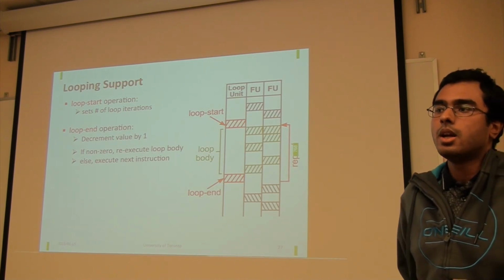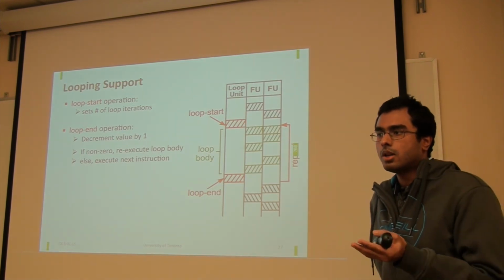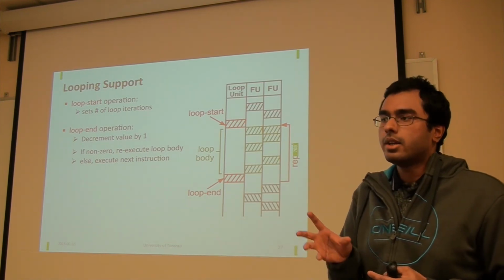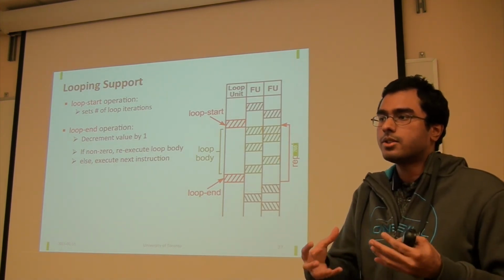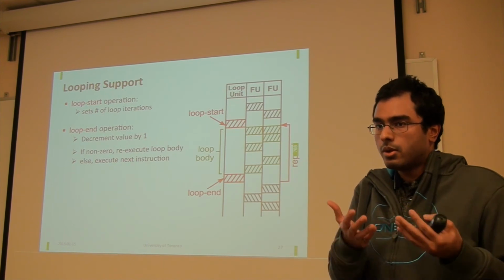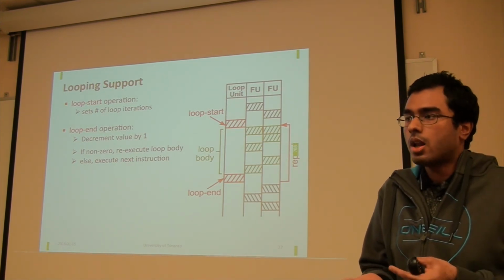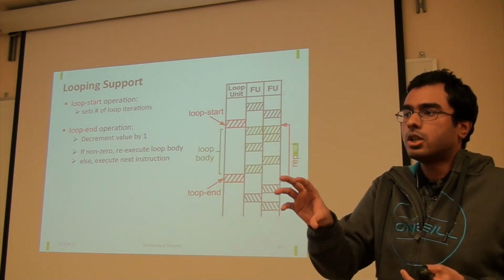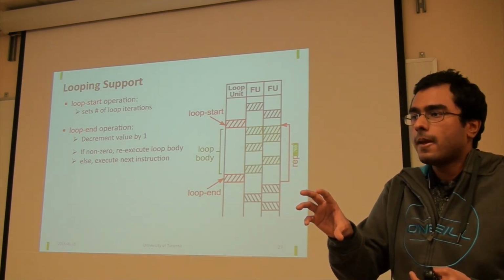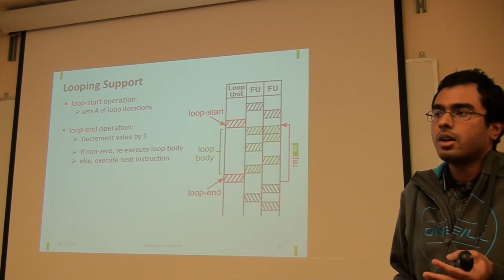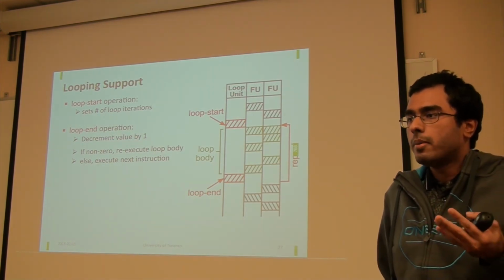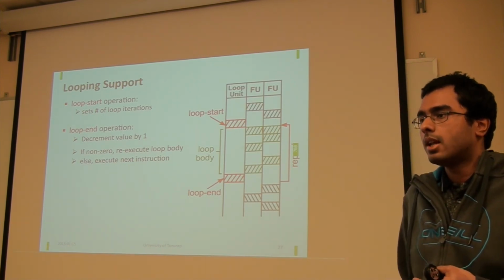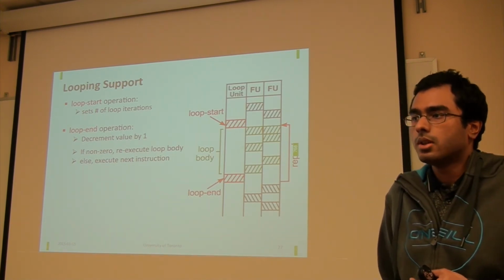Another thing, which Professor Betz alluded to, is how to integrate the tilt core, whose main point is to be small and area efficient and to reuse the existing functional units, as one of the IP cores in the OpenCL compiler, and see how that works.